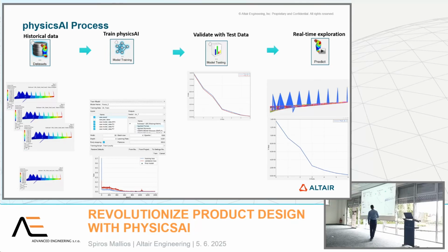And we train a model that is going to predict the shear moment diagram, these curves here, basically. Once we have a model that can predict the shear moment diagram based on the forces and the wing shape, we can use this model to do basically the reverse thing. We can input a new curve, and we can ask our solver, okay, what would be the loads that are going to equate to this?